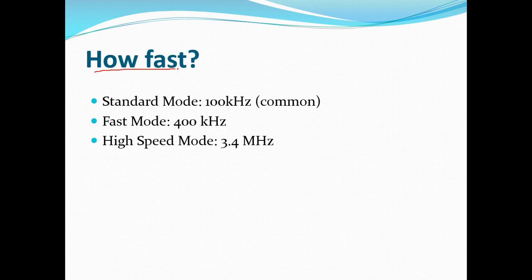How fast? Okay, this is important. For standard mode, the frequency is 100 kHz. Very fast, huh? You can calculate the clock period: 1 divided by 100k gives around 0.01 millisecond, which is around 10 microseconds.